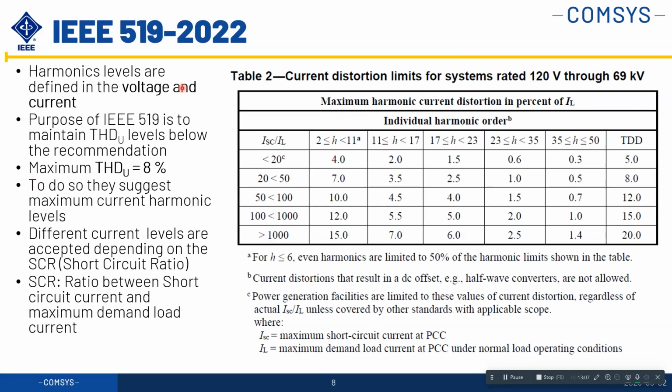If you look into the standard, you will see that the main goal for the IEEE 519 is voltage distortion. So we want to limit the voltage distortion to below 8%. Exactly what we said before, to protect your neighbor, because the voltage distortion is visible at your neighbor's place as well, not only at your place. The current distortion is only visible at your place, but the voltage distortion will travel over to your neighbor.